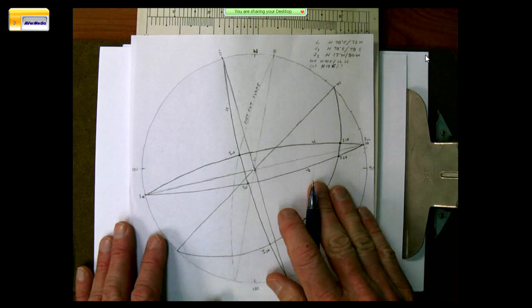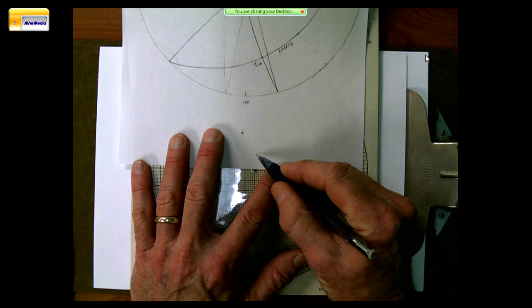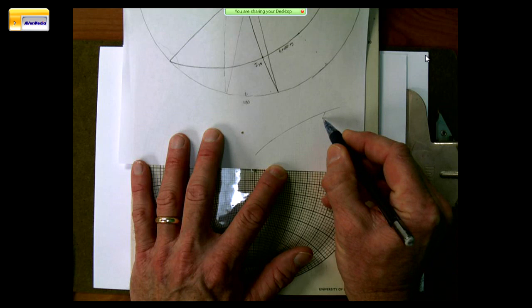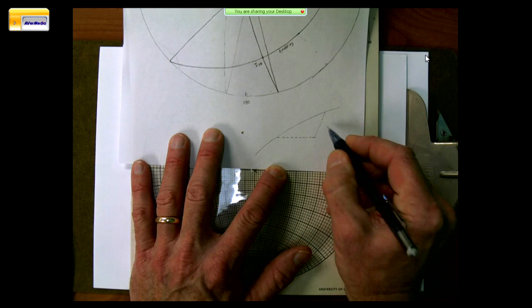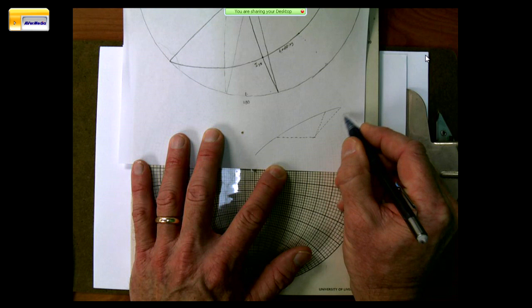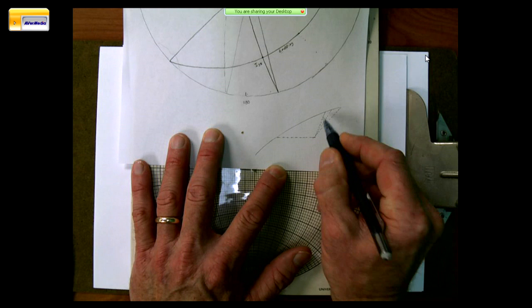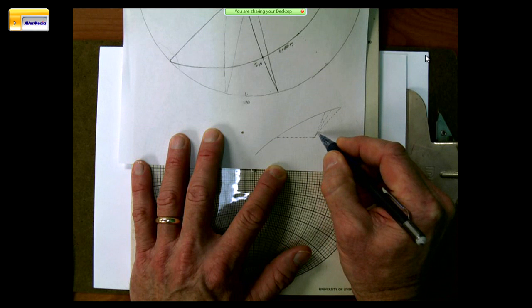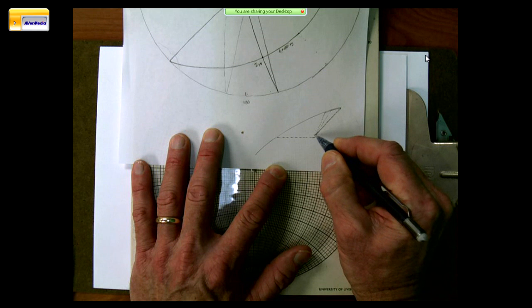Now what we're trying to do here, let's look real quick. I'll draw this for you. I've got a slope, let's say it looks like this, and I'm going to cut it here for a highway. And I have various intersections like that. Some are like that, and some are even steeper than that. So I can make this cut up to the point where I daylight that wedge right there. And that wedge can slide out on me.